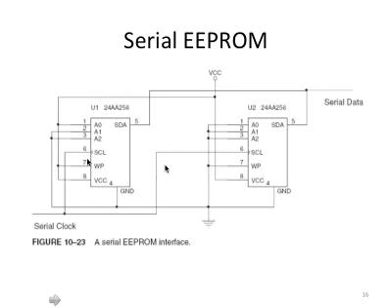First, you can see these two chips are identical. In order for them to operate, they have to be connected to power, of course. So you can see VCC is connected to VCC on both of them, and ground is connected to ground. The second thing I want you to look at is the address.